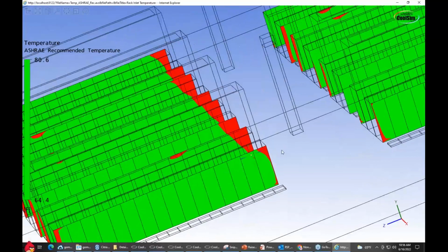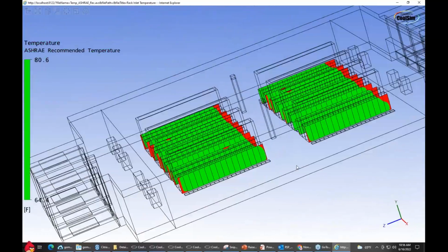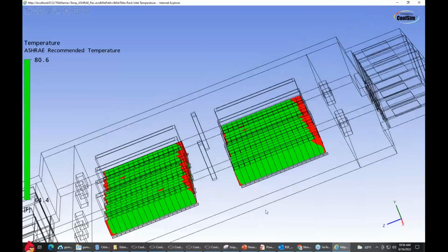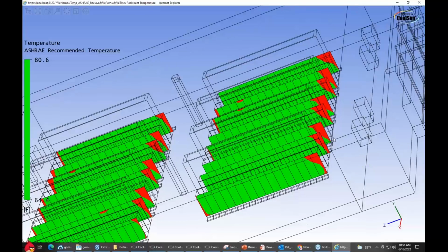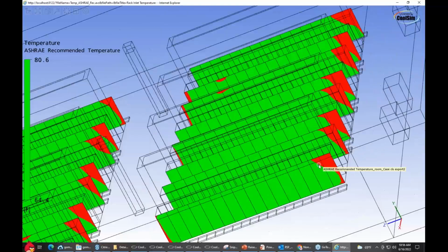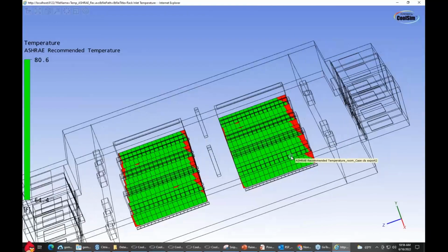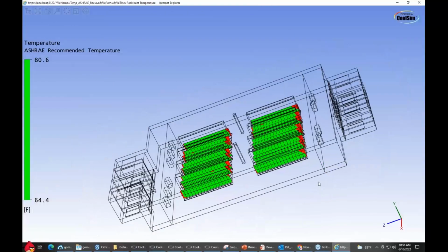But when I see a design like this, I say, well, that's manageable. One of the things you can do is be careful of those racks. Don't put 8kW there. Save it for the center. If you are going to put 8kW there, then you have the opportunity to add another tile in the center, make the tile higher percent area open, use performance tiles. So this is manageable. Plus, in the N+1 case, it's just much better.